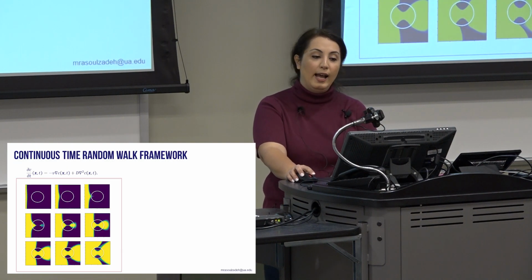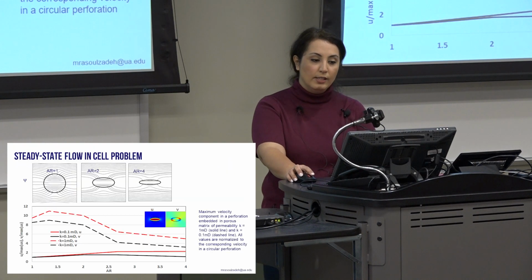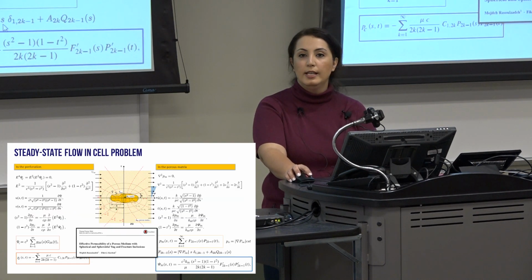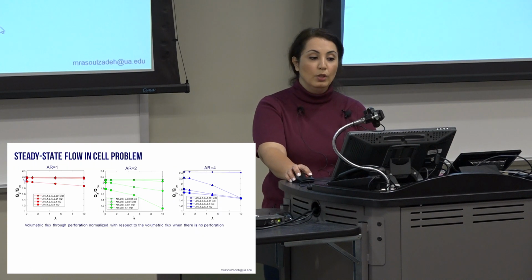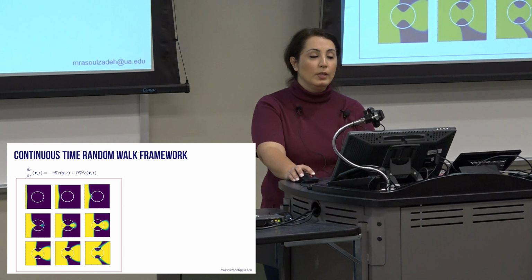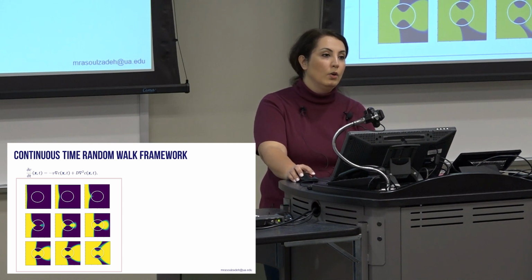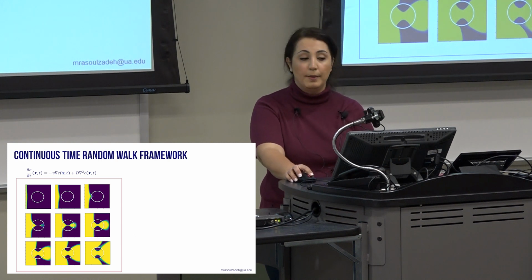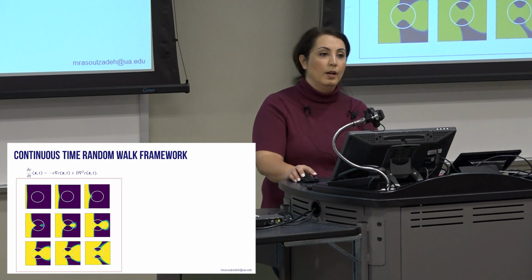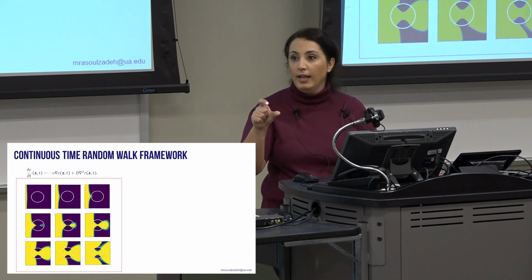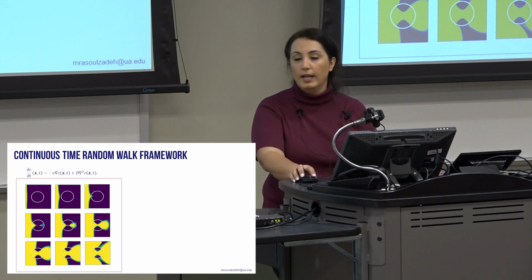So now that I have the velocity and stream functions, all the information is available for me to start looking into the transport process. So what happens for the transport? I have a high velocity here and a lower velocity here. So I used a semi-Lagrangian approach. That is, I go over streamlines for the advection and then just diffuse a little bit.